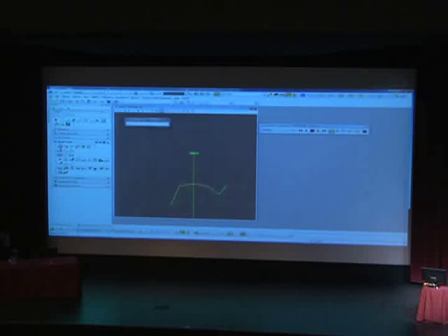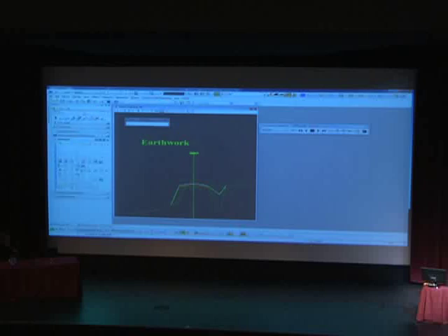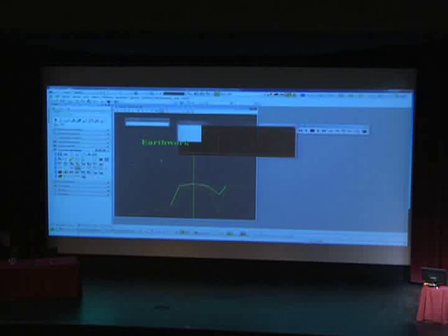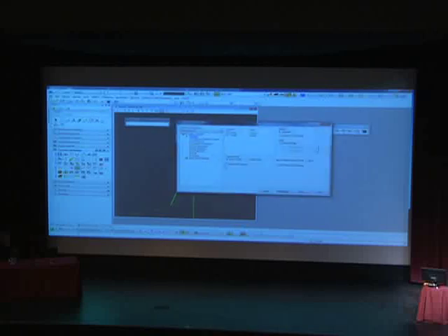Now, the thing that's going to be a little bit different though is earthwork. So for earthwork, if you go with this new method, you're going to have to use the new earthwork procedure. And that's just because, like I said, these shapes are all created from their corridor model, and we're used to having just undercut lines. So unless you're going to go draw each and every undercut line, that's up to you. I wouldn't recommend that, probably.